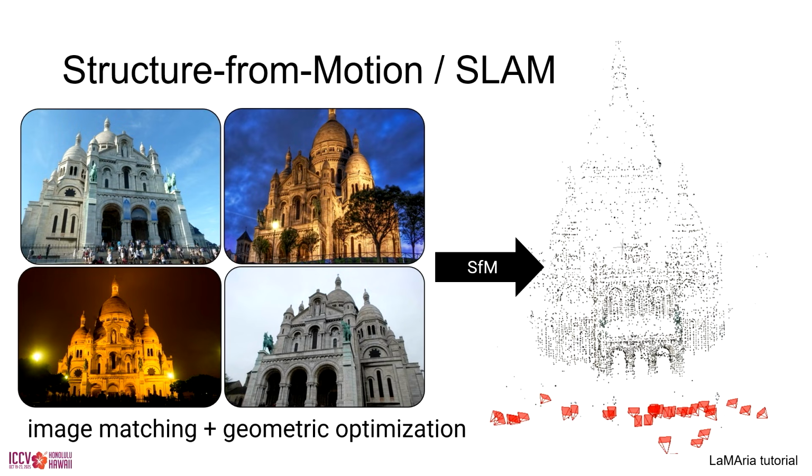In the computer vision community in particular, we have these two very related problems. One is called structure from motion, the other one is called SLAM, and they're in many ways closely related. SLAM comes typically more from the world of robotics. Simultaneous localization and mapping means that we haven't pre-mapped and then localize towards the map, but rather we start a session, start building a map, and then continuously relocalize to the same map.